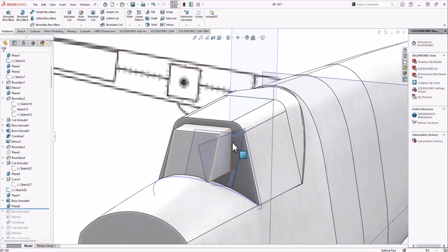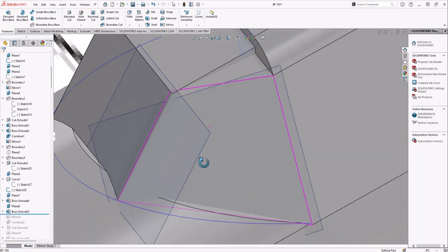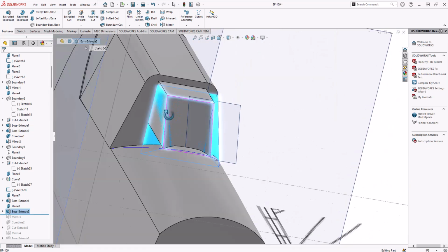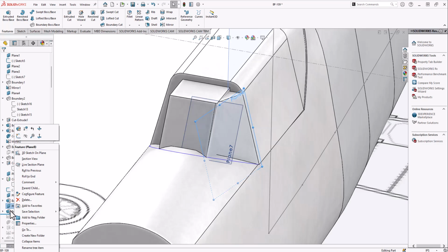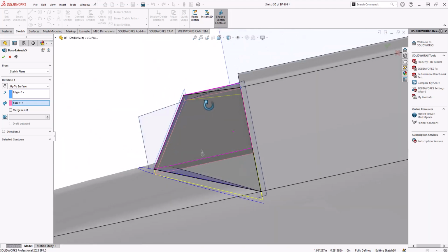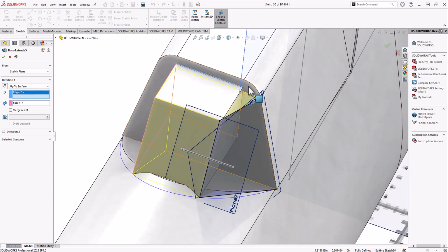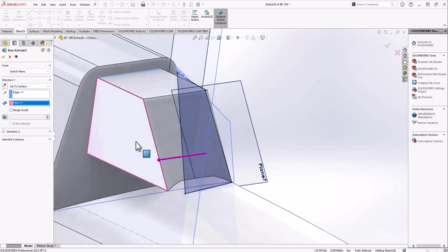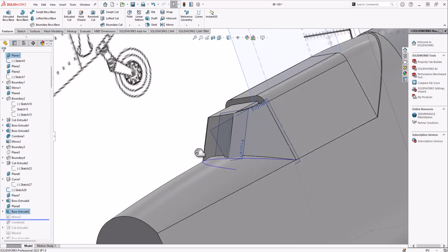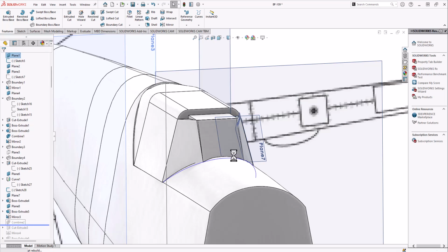So that's nice. I have this sketch, and then I draw on that plane, sorry, and I extrude backwards through to this edge along this direction. So what that looks like is I've got my plane, I've got the sketch on the plane, and I'm extruding in this direction. So not normal to the sketch or the plane, but along that direction, and it goes until it hits this face. And I made it so it didn't merge. That way I could duplicate it with a body mirror to get it to the other side. And then I just combine them to make them one piece.